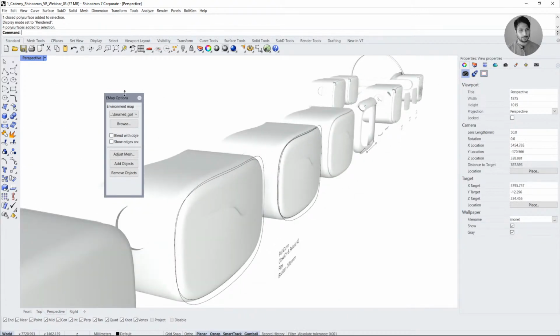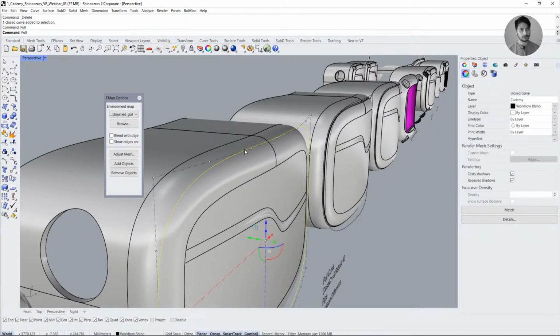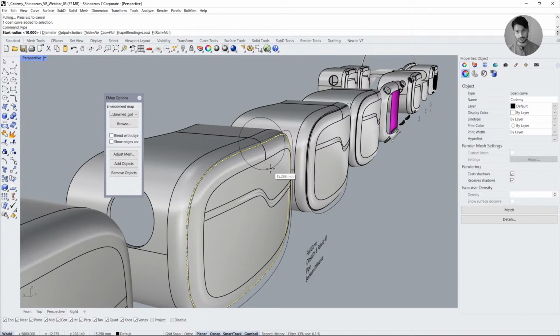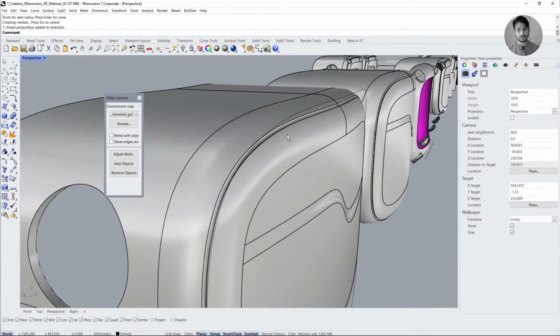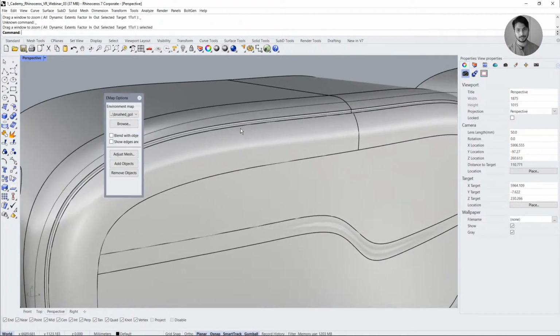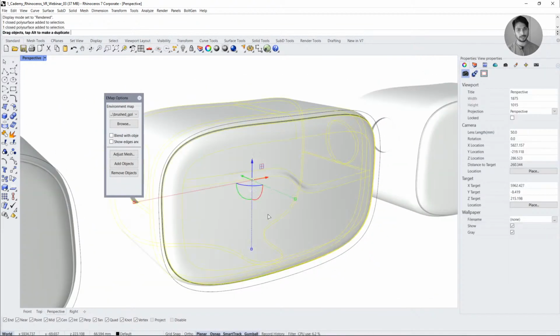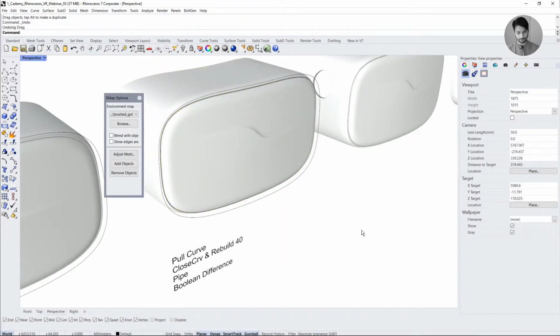And lastly, to add the cut on the profile, you can pull the original curve to the surface, and you can run pipe, let's say 0.5 millimeters on the surface, and you can perform the Boolean operation to get this nice separation point on the front part.